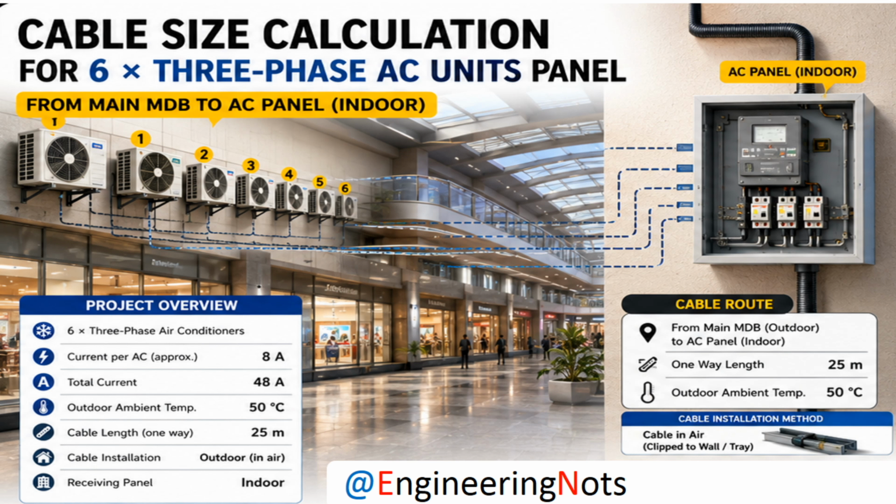The panel itself is installed indoors, but the incoming cable runs from outside the building to the panel. During the summer, when the air conditioners are operating, the outdoor ambient temperature can reach 50 degrees Celsius. Each air conditioner draws approximately 8 amps. And the distance from the main distribution panel to the air conditioning panel is 25 meters. So, now that we know all the important information, let's determine the cable size step by step.